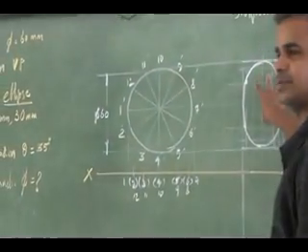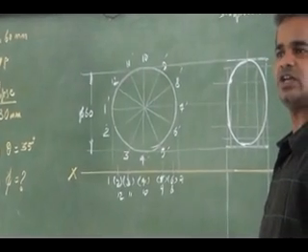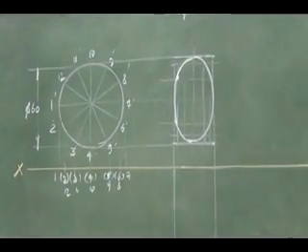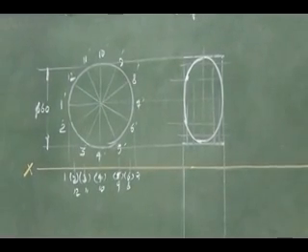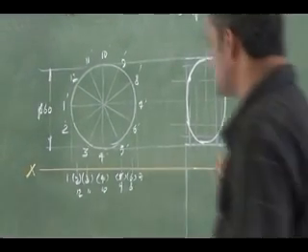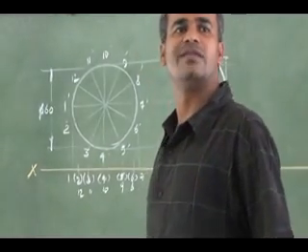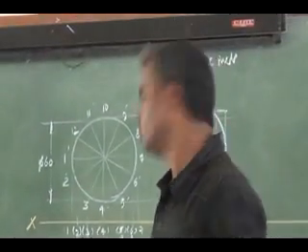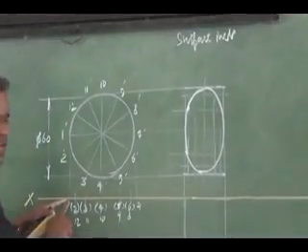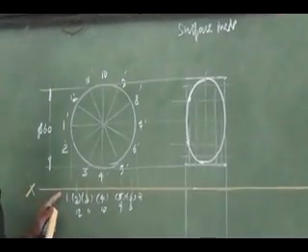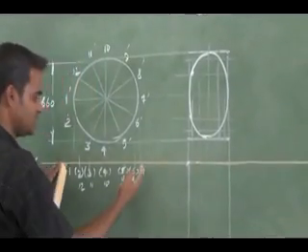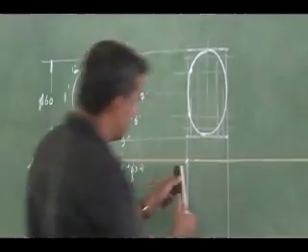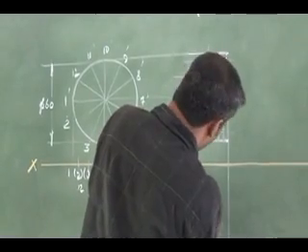So you know this is an ellipse. I can get the inclination of the surface in the second step. That is similar to this. Here you had the theta inclination in the previous problem. Here you should get the phi inclination. So what is this inclination? It is resting with the circumference point 1, so that 1 I can mark on the reference line. So what is this distance? I can measure it, and I can cut it on another locus.